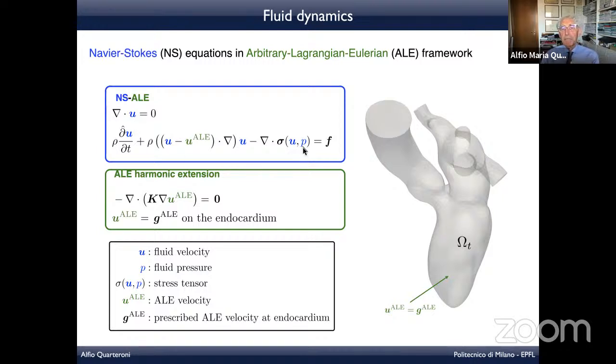And the other one is p, which is the pressure, which is actually a Lagrange multiplier for the constraint which is given by this equation. This equation is divergence of u equal to 0. It expresses the continuity. It's called the equation of continuity. It is expressing the conservation of mass. So you have the continuity equation for the conservation of mass, and then these equations, which are vector equations for the conservation of linear momentum.